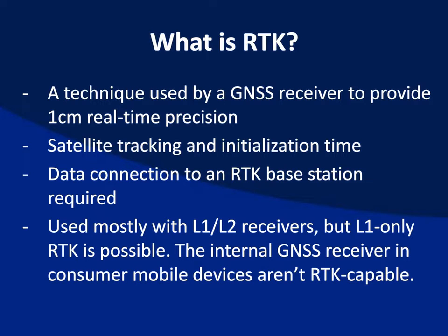And there's only so many up in orbit that are broadcasting at the moment. At any one time, there's maybe 20 max between GPS and the Russian GLONASS satellites, and then if you start to chip away at that with blockage, you may get down to 10 or even less than that, depending on the environment. And it just makes it much tougher for that initialization time to be practical. So those two things make it a challenge sometimes to use RTK in challenging environments. And it frustrates users sometimes because lots of users don't understand that that's the issue.